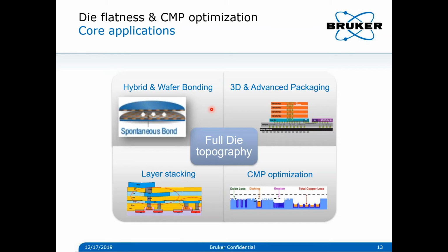And by splitting the two wafers, we avoid metallic contamination to the pixel side and make the pixel more efficient. However, you will have a molecular adhesion bonding between two wafers. In that respect, you will need this die-to-die flatness, such that adhesion can occur and be reliable. So in that case, there's a need to stitch the full die and assess how flat it is.